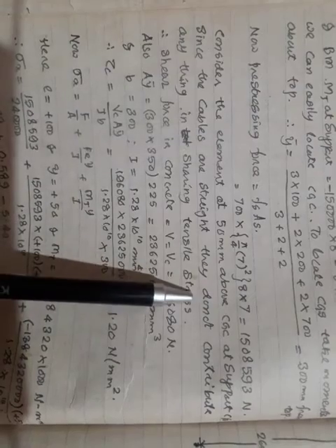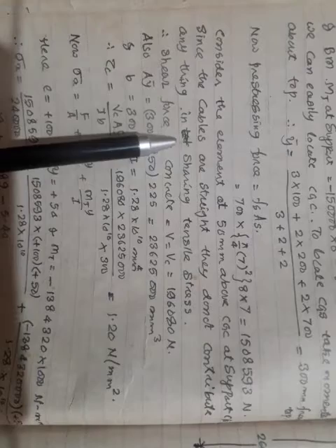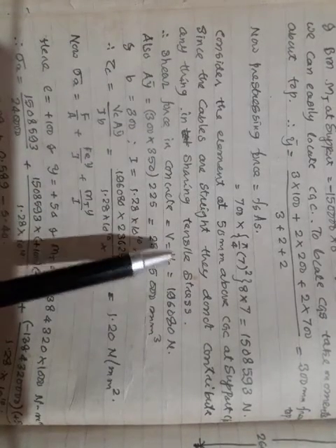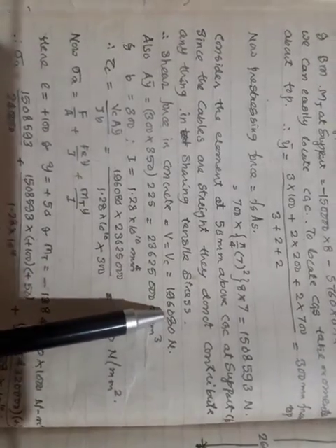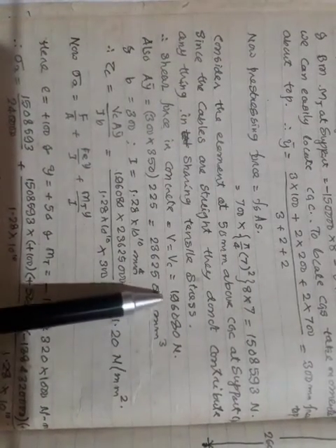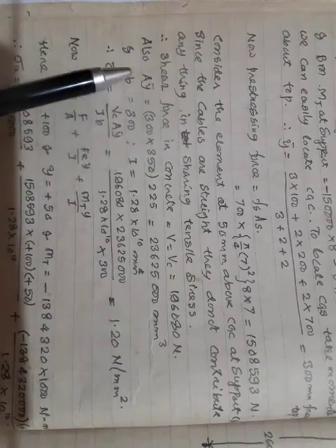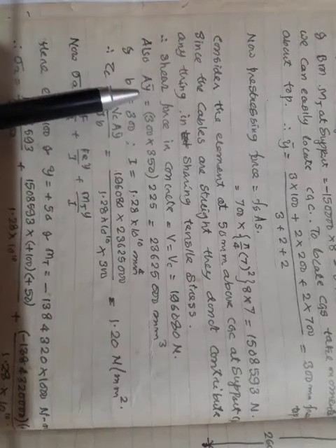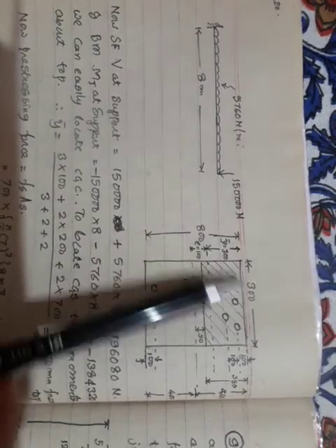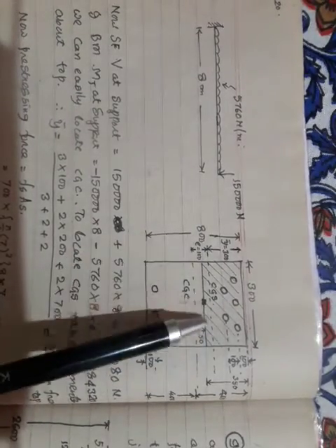But now, since the cables are straight, okay, they are not going to contribute anything to the principal tensile stress. Am I right? Therefore, shear force in concrete is V is equal to Vc. In the sense, whatever we have calculated earlier, shear force, same thing, it will remain. Okay, 1960. Okay, 1960 itself is your shear force in concrete. And by A y bar, I think I can easily calculate. A y bar is, it is the hatched area. Element is now here. This is the area above this.